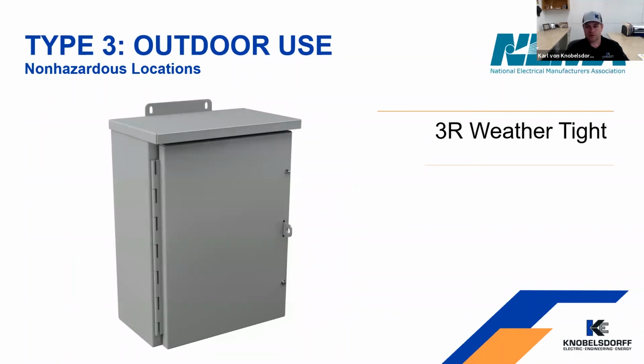This is a Type 3 weather type box. You'll see these installed outdoors a lot, and that's what they're made for. We also see this installed incorrectly indoors in a dusty location a lot of times. This box is not designed to keep out dust. This box is designed to keep out basically water, rainwater. So if you've got boxes like this inside your facility with no gasket, that is an incorrect installation. It is not rated to be installed in a Class 2 Div 2 or Class 2 Div 1 environment.